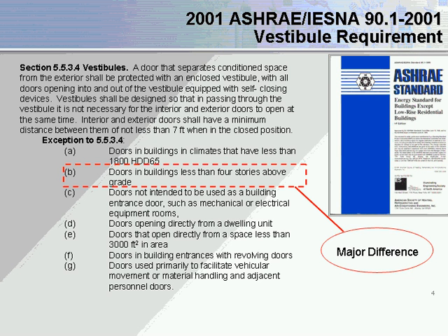One of the questions that comes up is how can I exempt my building from the vestibule requirement? This is probably the biggest exemption, but bear in mind that if you comply and take the exemption with vestibules in 90.1 2001, it means that you also need to follow the envelope requirements within the ASHRAE standard and complete them in its entirety.